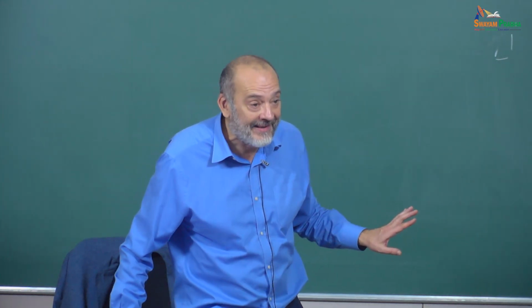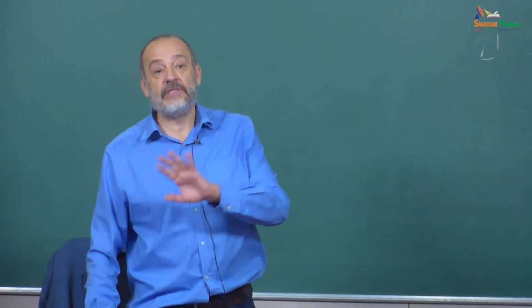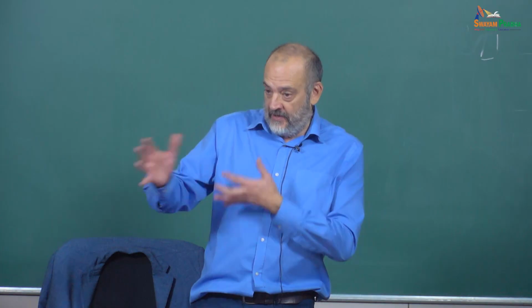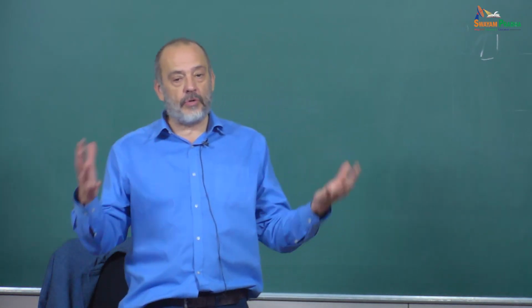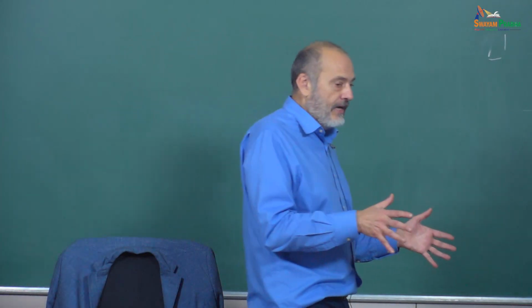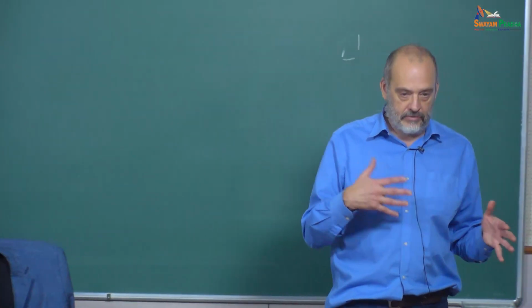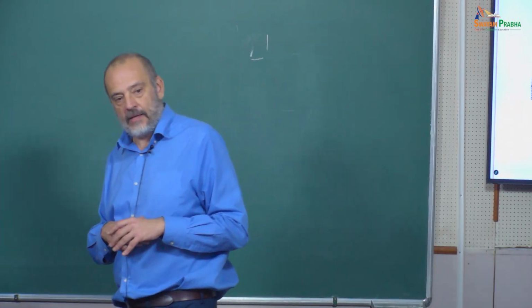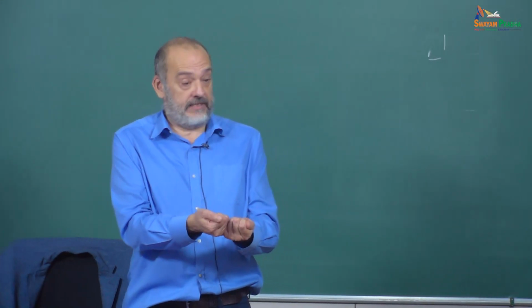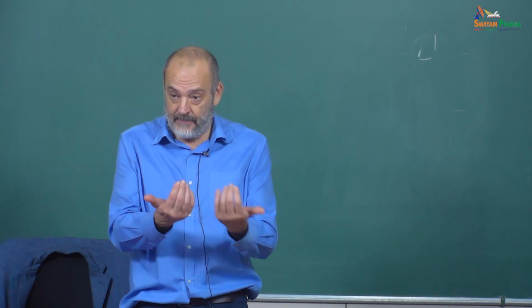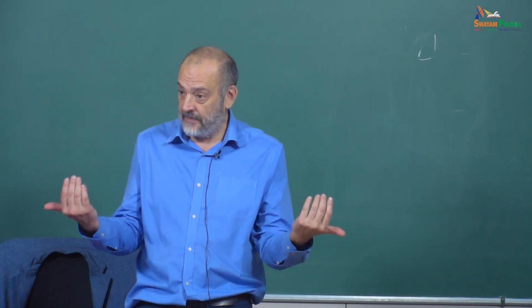And this is for water, and we know water very well. If you're considering other fluids, it's worse. So the deviation between different models is really huge. Okay, so pay attention when you're doing experiments or simulations close to the critical condition to have the right properties, or maybe try a sensitivity analysis to understand what is happening with the different models, because this can be really important.